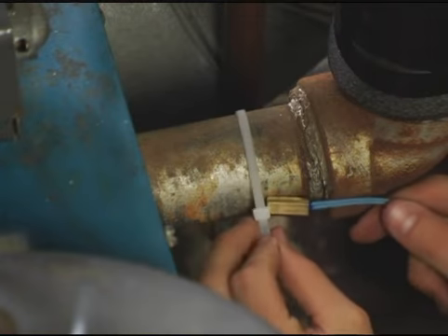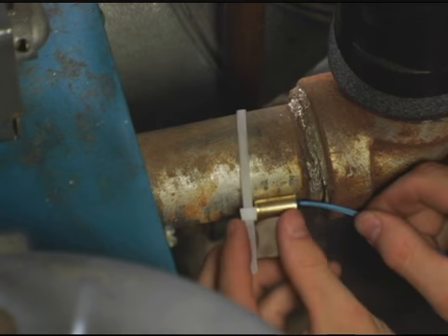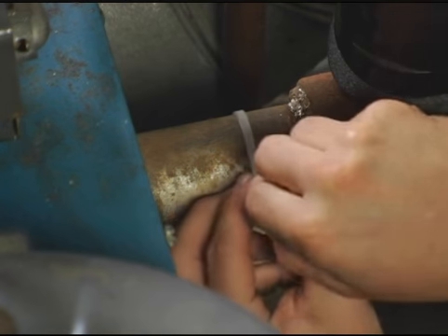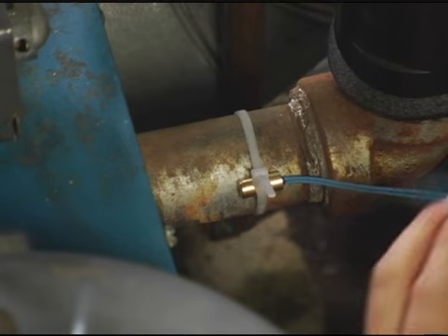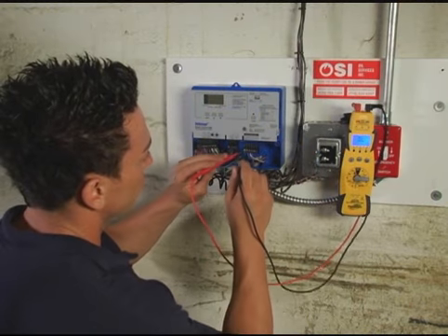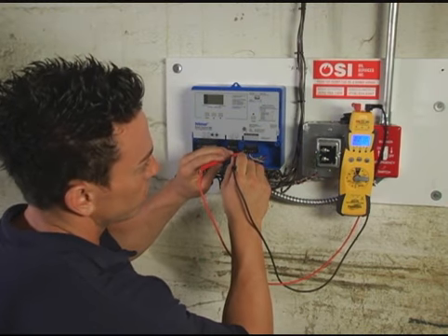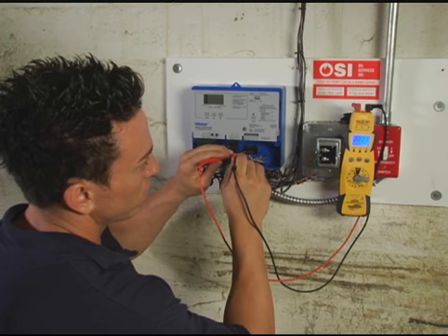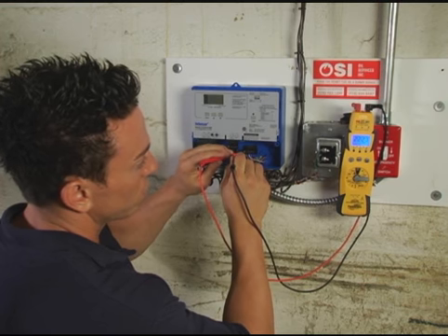Where a digital thermometer is not available, a spare sensor can be strapped alongside the one to be tested, and the readings compared. First, measure the temperature using the thermometer, and then measure the resistance of the sensor at the control. The wires from the sensor must not be connected to the control while the test is performed.